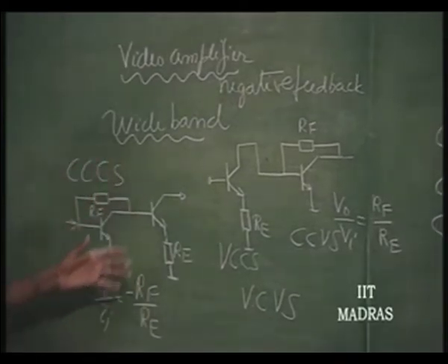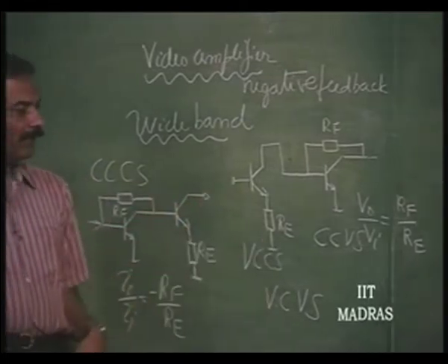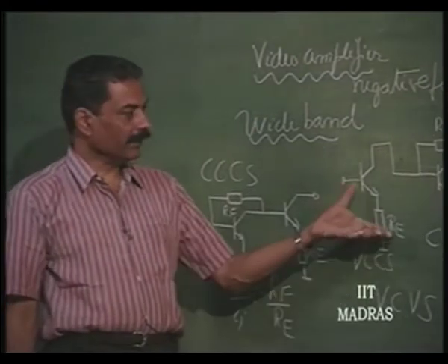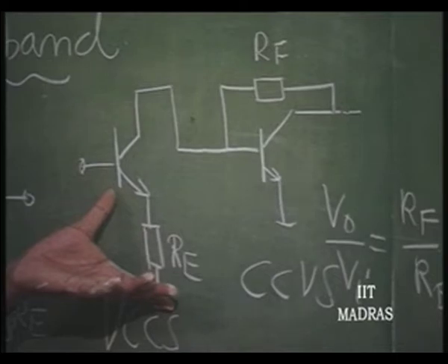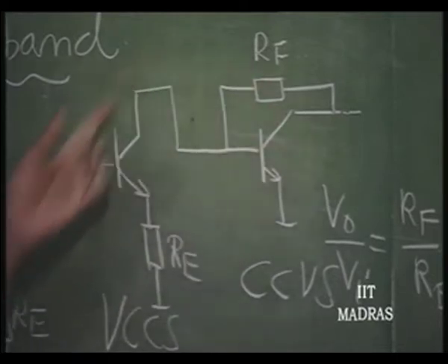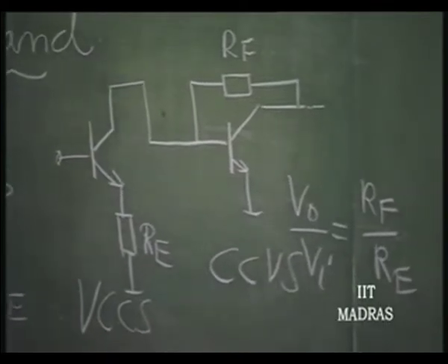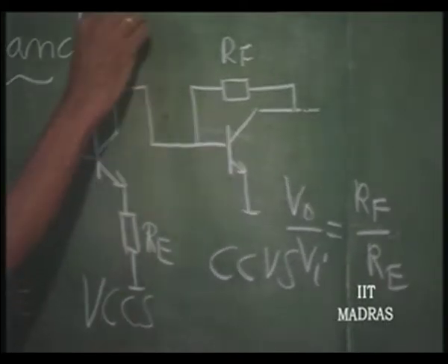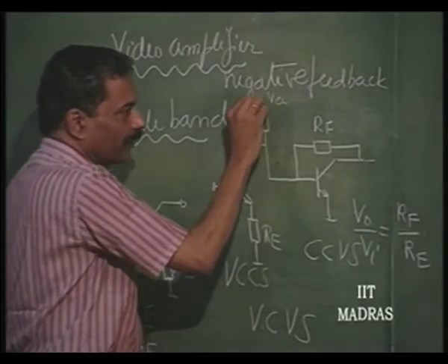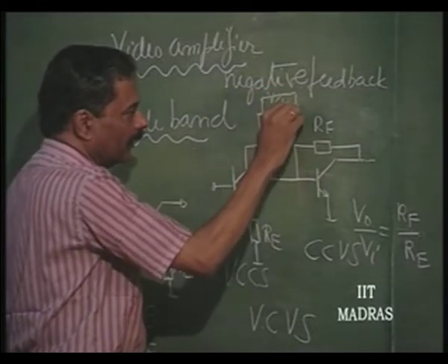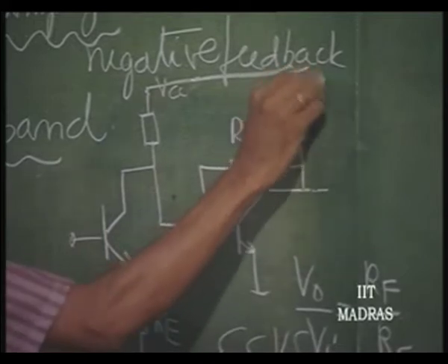The only thing is, you can convert these structures, for example, into an IC by simply converting this stage into a differential stage. For biasing purposes, this whole circuit can be converted into a differential structure. So, I would just want to indicate that for biasing purposes, you have to put a resistance from here and a resistance from here to VCC.